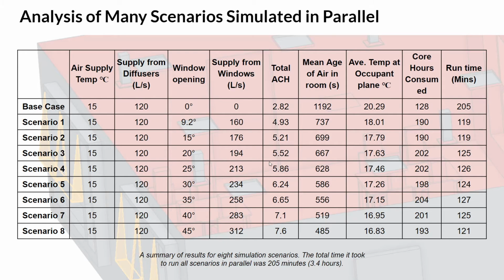And we can see that with the increased window opening area, we have a much lower mean age of air. So it would be much more favorable for the occupants to be in these conditions with COVID restrictions.